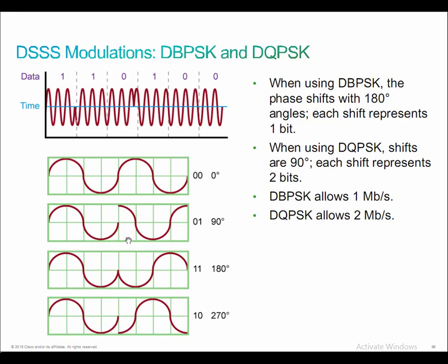So the angle, whether it's positive or negative, doesn't really matter in this particular case, because it's a shift of 90 degrees. That's what defines the 0, 1. Okay. If the group to transmit is 1, 0, we see that at the bottom. We're going to turn 270 degrees or minus 90 degrees. So the opposite of the 0, 1 sequence. If the signal is going up, suddenly we should carry on from the bottom. If the signal wave is going down, carry from the top. Same concept, still represents the same bit pattern or bit sequence.